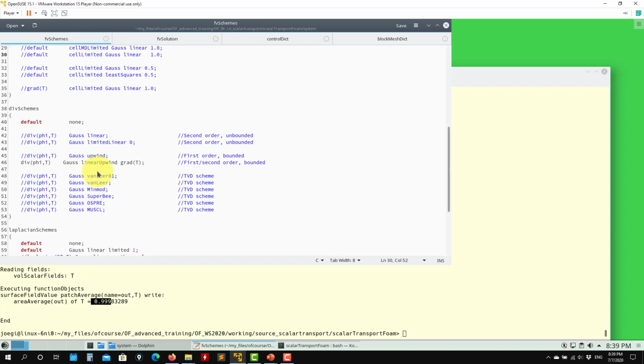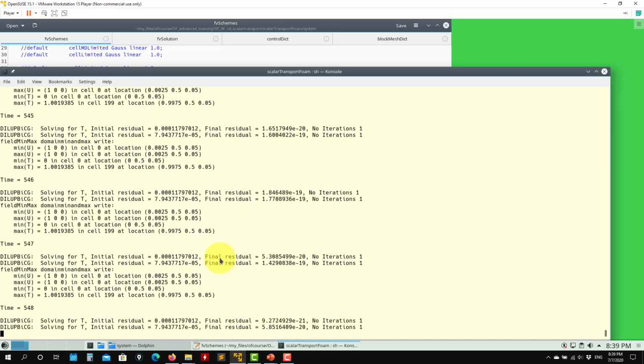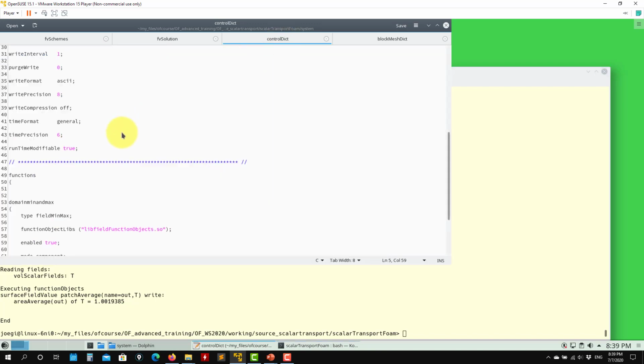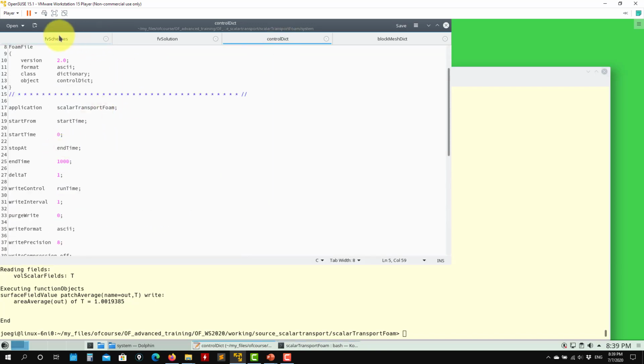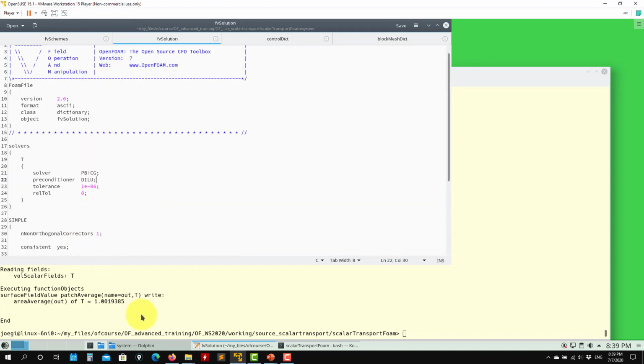And let's play now with the numerical scheme. So now we're using the linear upwind, the one that I recommend you most of the time, but let me go and change to Van Leer. So let me use now Van Leer there. Let me run. And see that Van Leer, first thing that is strange, you will see that you are taking all 1,000, the maximum number of iterations that I have in control to converge. So it's already telling you that maybe there is something that is not going very well there.